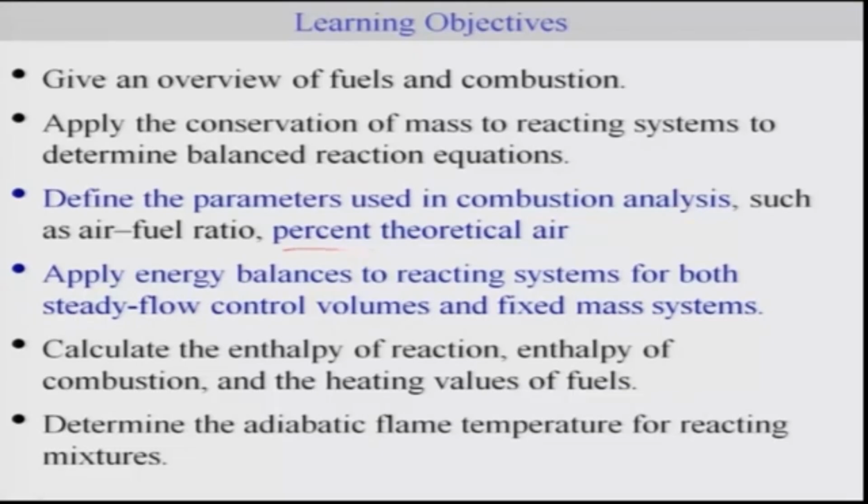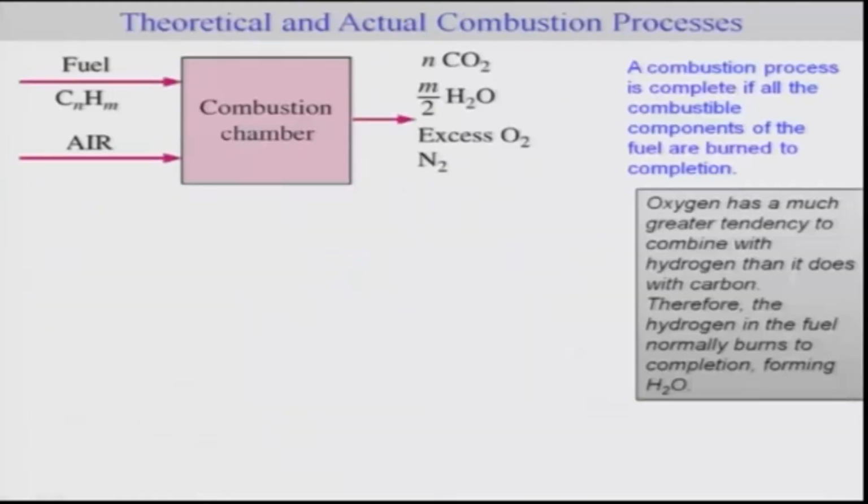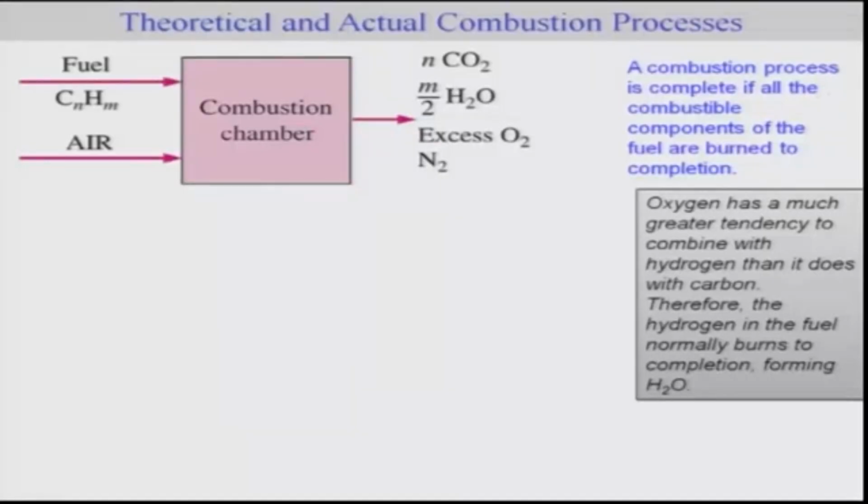particularly the percentage of theoretical air, and we will try to do some energy balance for reacting systems for both steady flow control volume and fixed mass systems. As we realized in our basic analysis, there is a possibility that some of the combustion cannot lead to completion, for example, if the air is not sufficient, or there is a possibility that excess air is given, so the combustion is complete but you still have some of the air left in the product stream. So a combustion process is complete only if the combustible components of the fuel are burned to completion. So this is kind of a theoretical estimate.